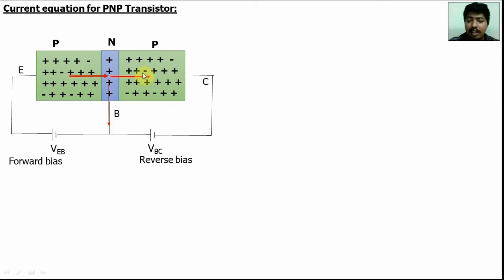It causes a current flow. Also, due to reverse bias, the negative polarity repels the minority carriers, which move to the base. Similarly, the base already has minority carrier holes. The holes move to the collector due to the reverse bias. Due to the minority carrier movement, there is a reverse saturation current. On the collector side, current flow is due to both majority and minority carriers. Both carriers means the movement of all the emitter electrons, and the reverse saturation current.